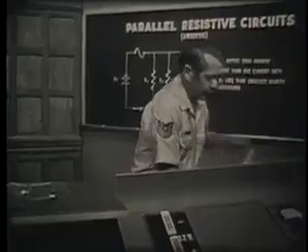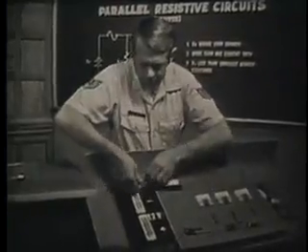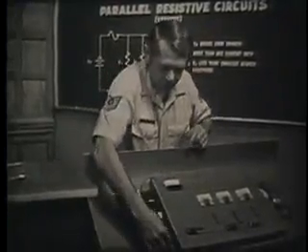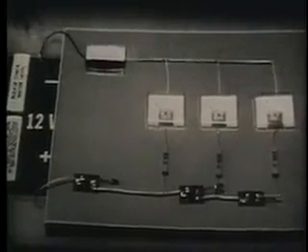And I'll use another trainer to show this. Making the power connections here. Okay, let's look at the current in a parallel circuit. Notice first that we have 4 milliammeters in the circuit. Also notice that the current leaving the negative terminal of the battery, all of the current must pass through this meter. Then we'll use it to measure the total circuit current. The other meters will measure the current in the individual branches.